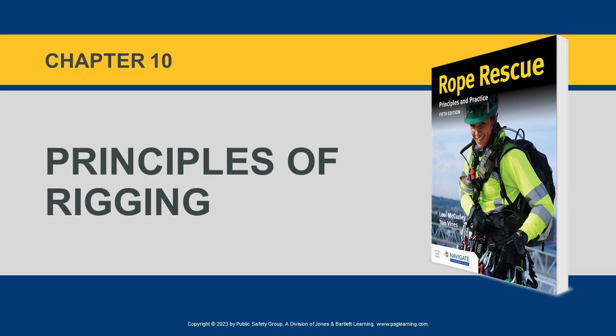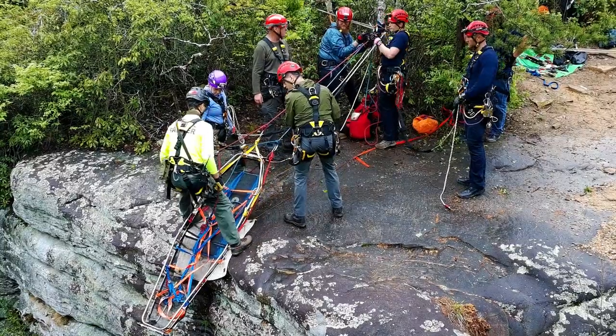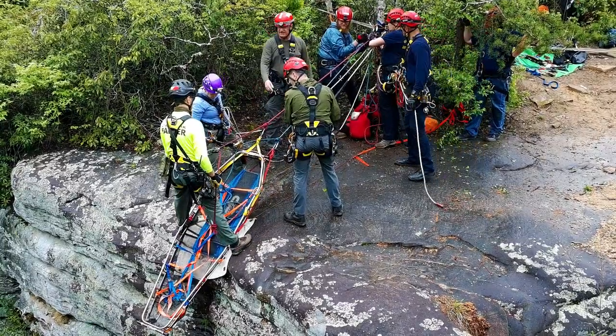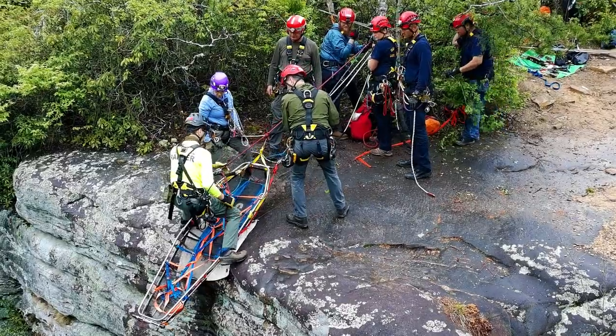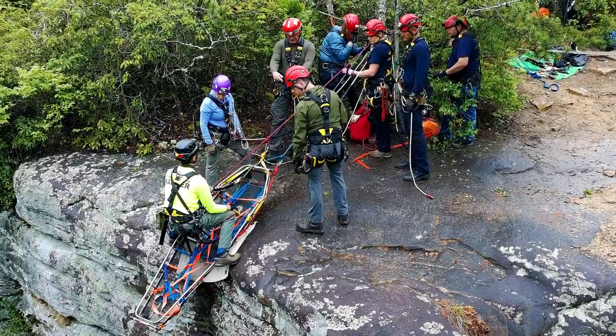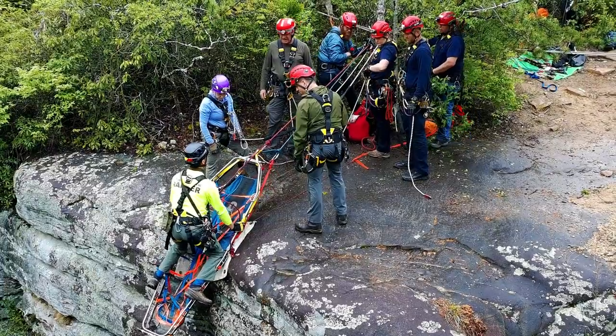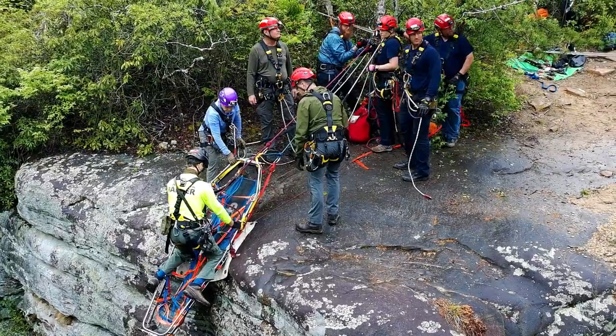Alright, let's wrap up what we've covered in this chapter so far. First and foremost, before you ever touch a rope rescue system, you need a solid understanding of forces and how they interact. Think of this like knowing the rules of the game before stepping onto the field. And remember that a vector is just a fancy way of saying a force has both direction and magnitude. Every force you deal with has a vector, and when multiple forces act together, they combine to make a resultant vector. Angles matter. In rope rescue, we care most about where vectors meet. Those intersection points are where tension can spike or be redirected.